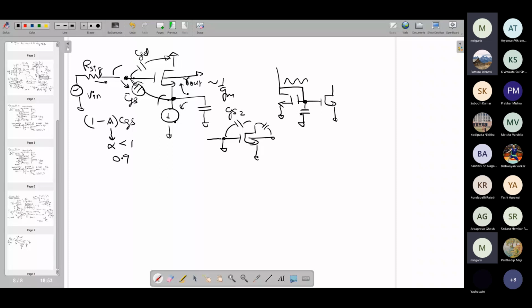Because this part is connected to the circuit, your common drain transistor is coming over here, and the signal is coming over here. This is the output. So this is your current source. This M2 is your current source. M1 is your input device. So this is the scenario, and second, M2's CGD is going to contribute and CDB is going to contribute, because both of them are coming as a gap between the output node and AC ground. Fine, that I can add.